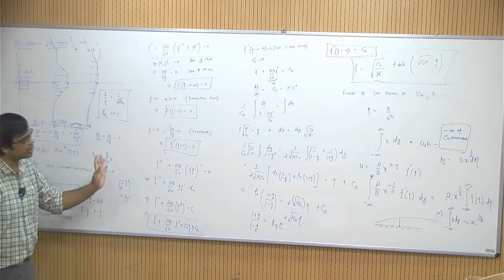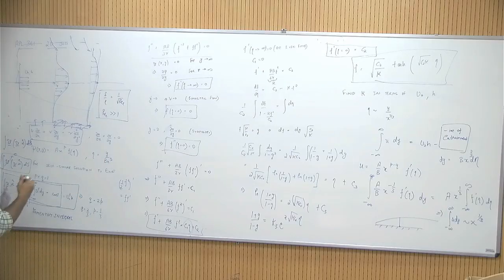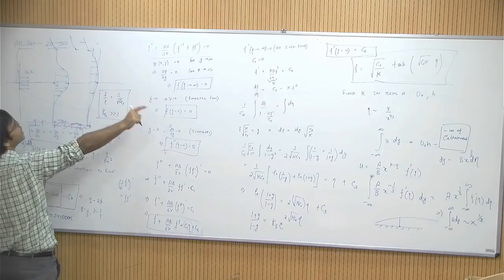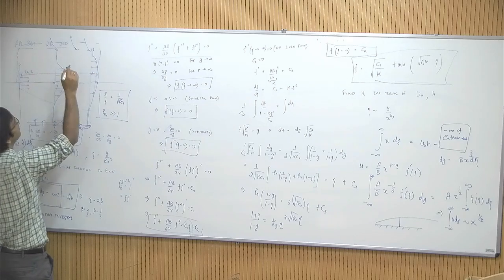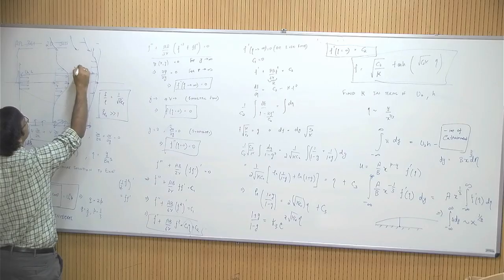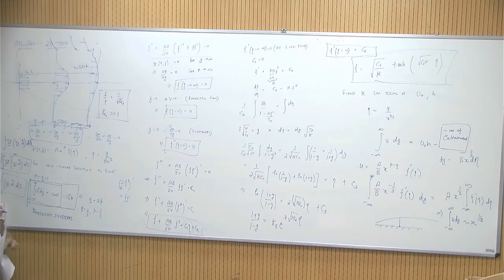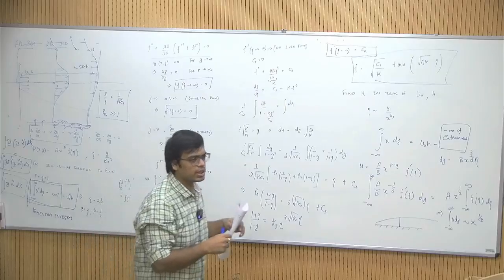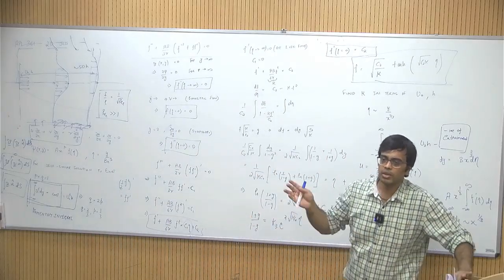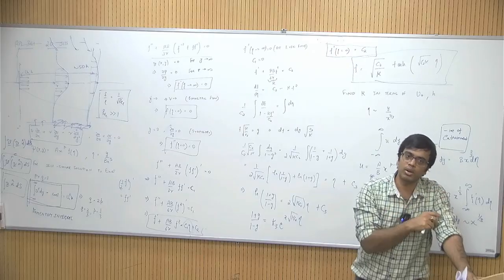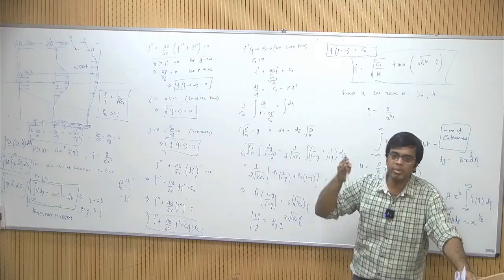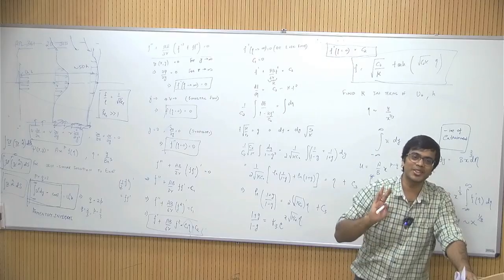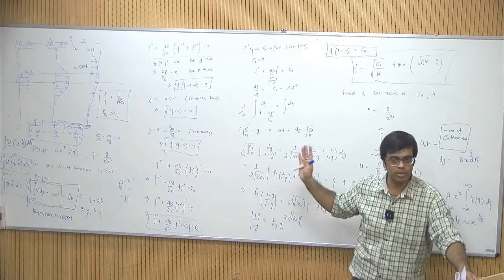All of this algebra gave us a closed form solution, and it happens in practice. You can actually experimentally validate this solution also, but you have to be sufficiently far from the jet outlet, something like 50 h to 100 h. If you are that far away, you barely see a jet if your instruments are not sensitive enough, and that is the regime technically we are solving. Very close to the jet, none of this holds.